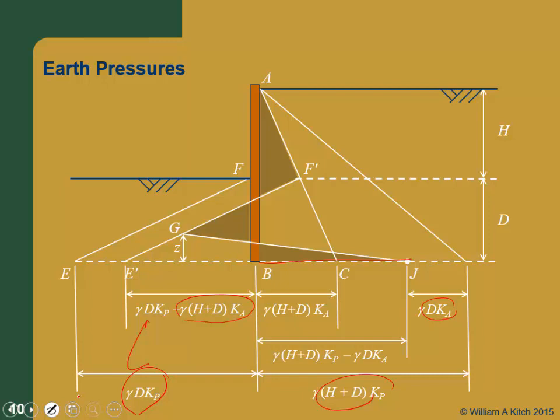I think there's two reasons this works. One is you actually do get quite a bit of movement in these walls when you design them, particularly if you're doing them in an environment where you're filling behind a marine environment. So you could get quite a bit of displacement and still have an acceptable design, so long as at the end you didn't have too much displacement. So I think that's one reason it seems to work okay.